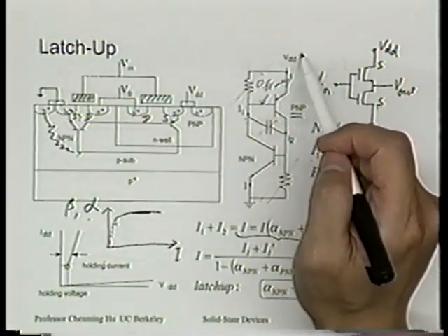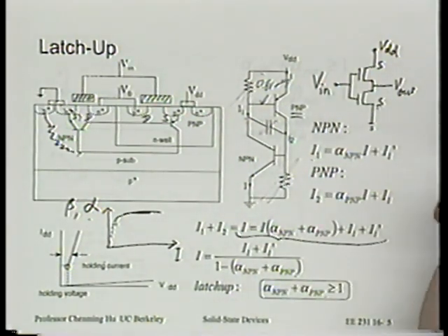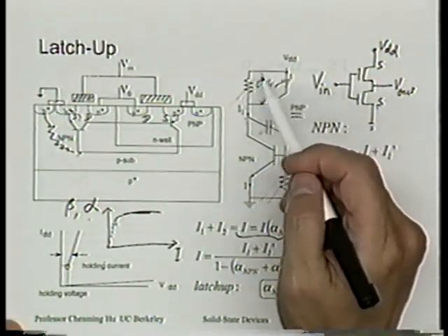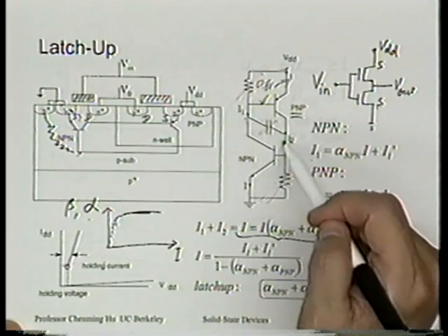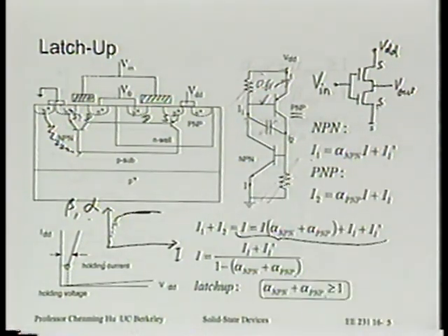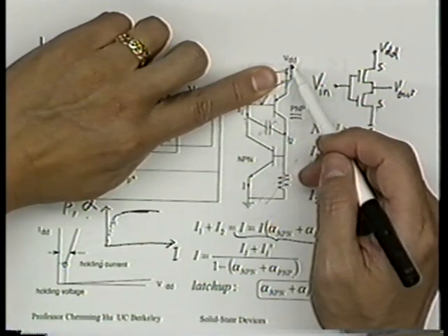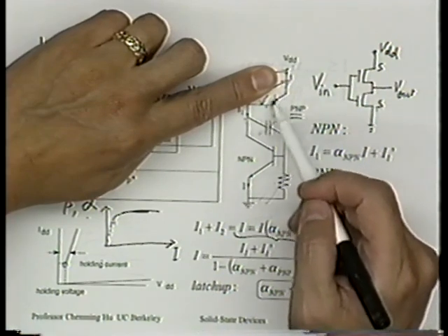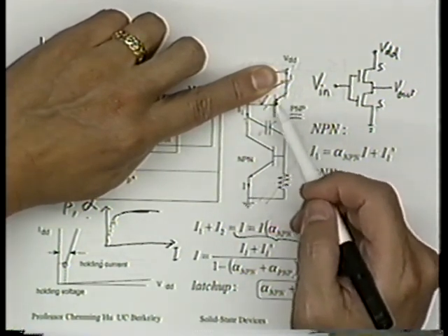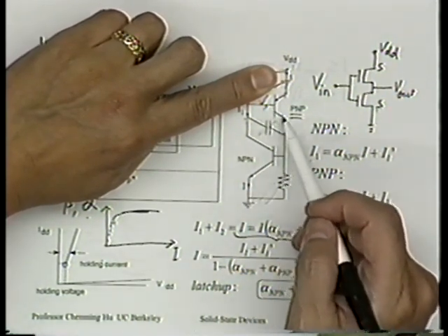When we suddenly apply a dV/dt, let's say suddenly turn on the power supply voltage, I used this example. Now, a significant amount of capacitor current can be allowed because it will flow through these resistors. If it flows through resistors, then the transistors are not turned on. You see that? Because otherwise, if this is not here, when we suddenly apply a large voltage, say from 0 to 5 volts, suddenly this is forward biased anyway. You see that? It's a PN junction. You see the arrow? This junction is forward biased. Normally, it's this junction between base and collector that's reverse biased, so there's no current.